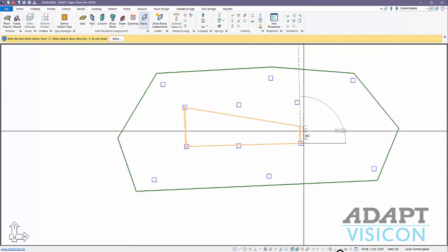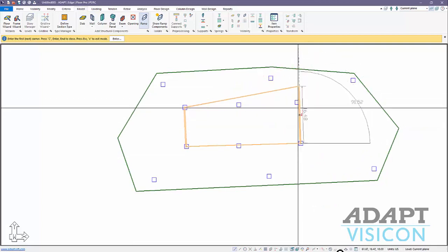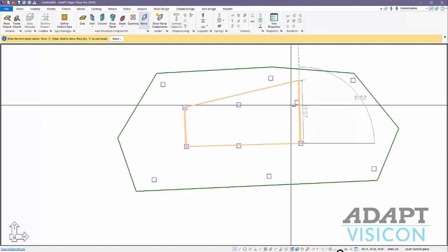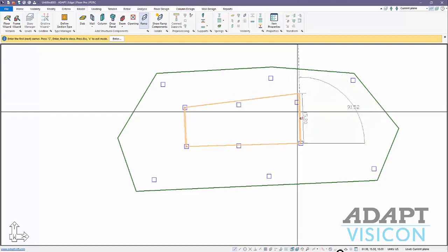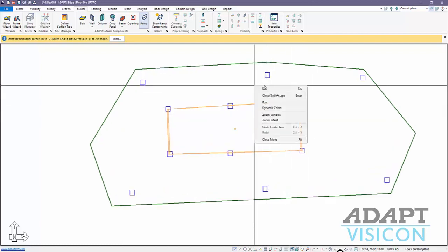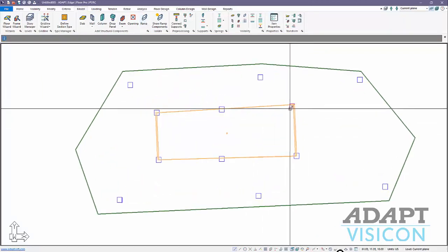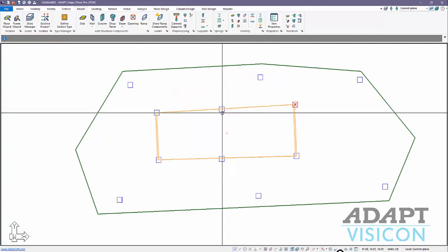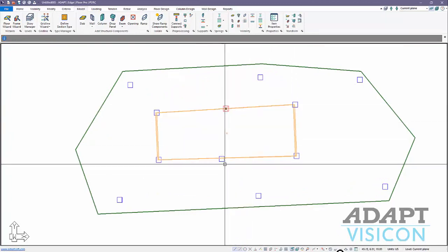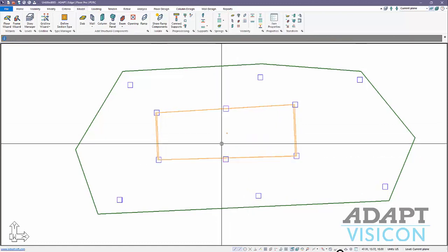And notice once we select the third point, this becomes locked. That allows the program to maintain just a planar ramp, which is a limitation where we have to model these as planar elements. So this becomes our ramp component. I'm actually going to move that column there, and I'll move this one just to the midpoint of the ramp, and this one also to midpoint.